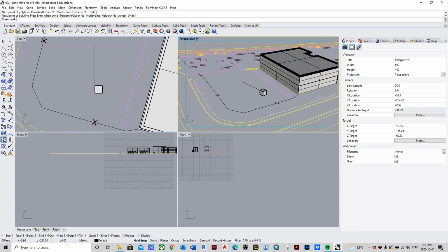So let's go back to the linear array tool. We'll move over to rectangular array, move down to the corner, select it. We're going to pick linear array over at the far right, left click, select objects to array. This is the object that we want, so we'll click anywhere on the cube, hit enter when done. You can hit enter or right click if you wish. Number of items, and then in brackets it says 8. Because we want 9 windows in the upper floor on this face, we're going to type 9 instead and hit enter.